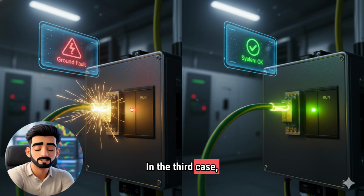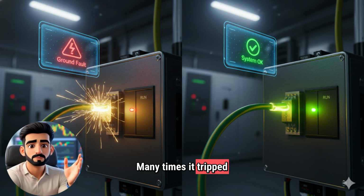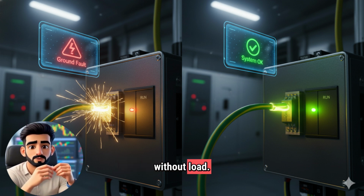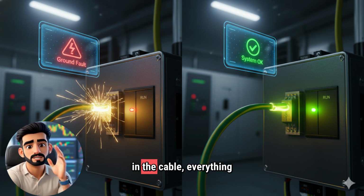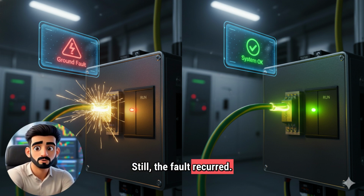In the third case, the drive was giving random ground faults. Many times it tripped at start, sometimes during load change, sometimes even without load. The team first conducted a motor insulation test, checked continuity and insulation in the cable. Everything was fine. Still, the fault recurred.